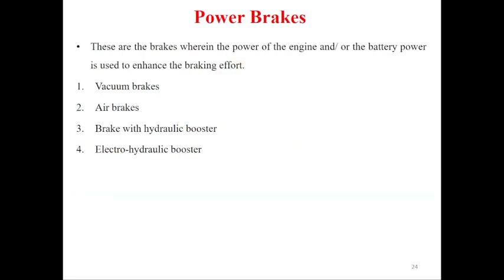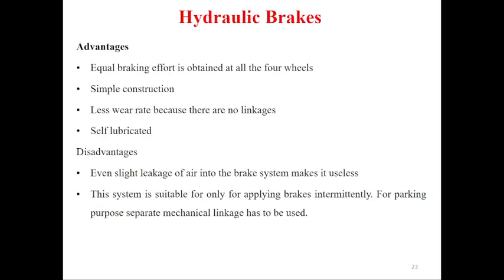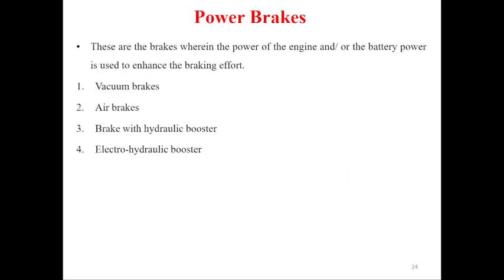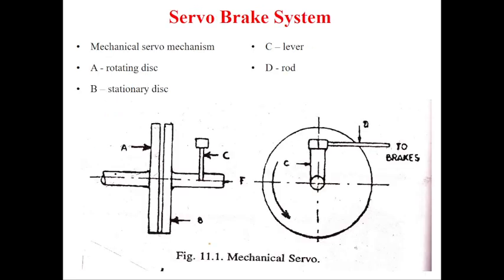Then the power brake. When we move from the hydraulic brake to the power brake, the power of the engine or the battery is used to enhance the braking effort. This is useful for the vacuum brake, air brake, brake with hydraulic booster or electro hydraulic booster. And for that we are using the servo brake systems.